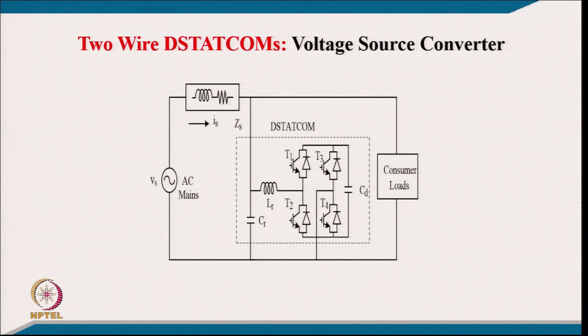This small capacitor is a part of a filter, and the reason we connect this CR after the LR is that the converter will be generating the PWM voltage at the AC terminal of this converter, and depending upon the source impedance, this LR, the interfacing inductor cannot absorb all the ripple, because the supply voltage is somewhere buried into the system. So, if the source impedance is higher, you will find a ripple across the load.